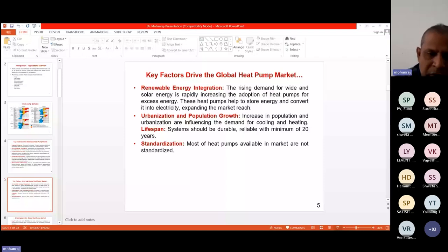So these are the environmental protocols which restrict the use of working fluids. These are some of the heat pumps developed in our laboratory for various applications. We developed a photovoltaic integrated heat pump for producing electricity. We are utilizing the evaporator for producing the cooling arrangement for the photovoltaic panels. This is utilized to power the compressor. This is a two-stage cascade heating system we developed in Kazakhstan to meet the space heating requirement in extreme cold climatic conditions of around -20°C.